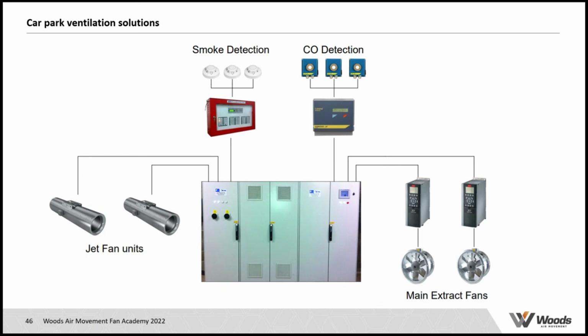So apart from the fact that as engineers, we are obliged to follow an approach where we also consider the conservation of power, it is actually something which will make the car park safer in terms of the conditions of CO in the car park, but certainly will also save a lot of money on the operational costs. So even though it's not specifically referred to in the building regulations, I always highly recommend the inclusion of a CO monitoring system because it gives you more flexibility and will certainly result in lower energy costs or running costs for the system.